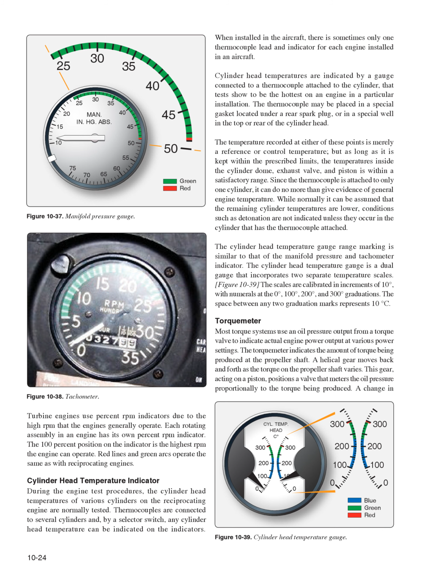Cylinder head temperature indicator. During the engine test procedures, the cylinder head temperatures of various cylinders on the reciprocating engine are normally tested. Thermocouples are connected to several cylinders and, by a selector switch, any cylinder head temperature can be indicated on the indicators. When installed in the aircraft, there is sometimes only one thermocouple lead and indicator for each engine installed in an aircraft. Cylinder head temperatures are indicated by a gauge connected to a thermocouple attached to the cylinder that tests show to be the hottest on an engine in a particular installation.